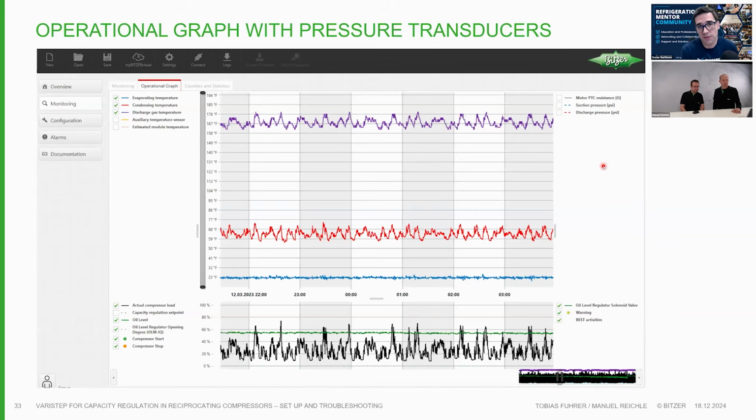There may be information from that very first guide that relates to the CO2 compressor, because once again, refrigeration is refrigeration. It carries over. We do not want liquid to go into the compressors. We do not want the discharge to run really high. And this is why the more manuals you read, the better information you'll have when you're doing the troubleshooting. Just like reading those trend graphs. It's so important in this one that you have here. Yeah. So this is now an operational graph.